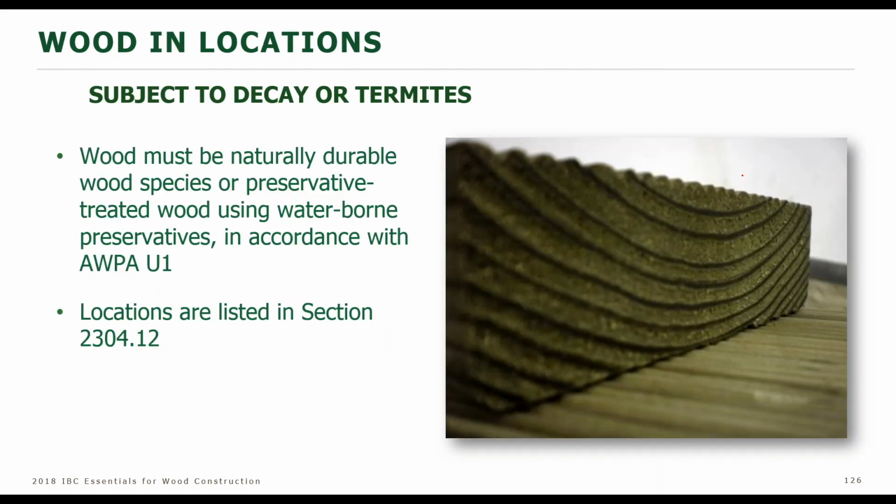All right, 2304 has a section on where wood needs to be protected by being treated with either pressure treatment for durability or for fire resistance, and the locations where that's required. So you'll find it in 2304 and also 2303. Separate sections for preservative treatment for durability, protection against moisture, and fire retardant treatment.